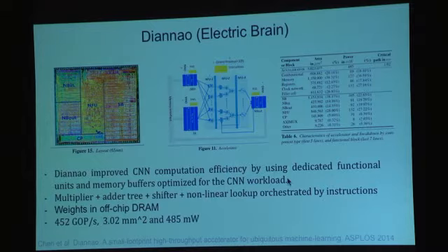You're fine. So people have been doing this for a while. A piece of work that got a lot of attention when it came out at ASPLOS in 2014, so it's February 2014, was DianNao, which my Chinese-speaking graduate students inform me means electric brain. So I want to know where I can get one of those. And it basically has a dedicated function unit for doing the multiplies and then summing the additions for both the fully connected and convolutional layers.